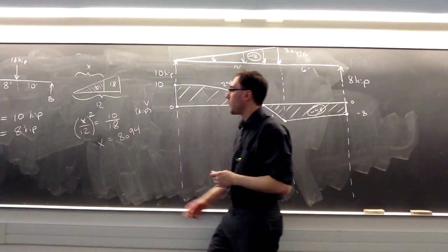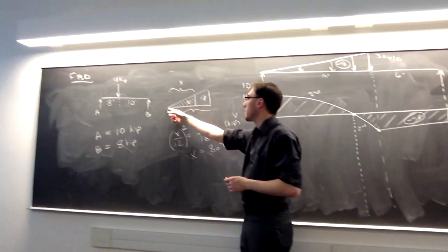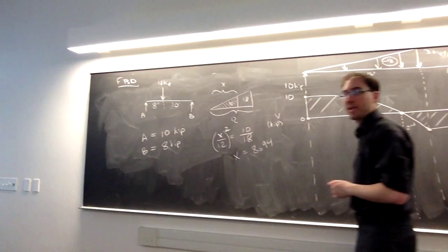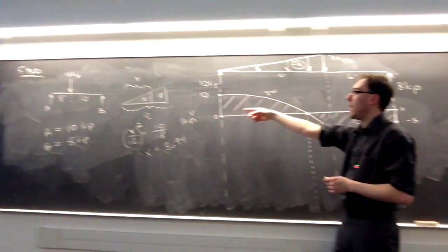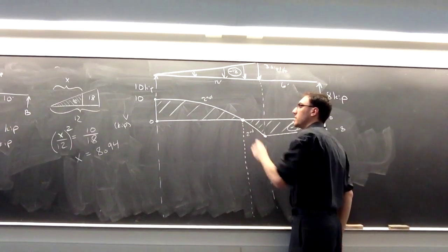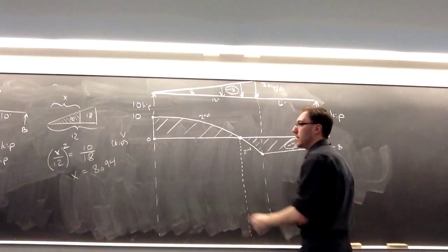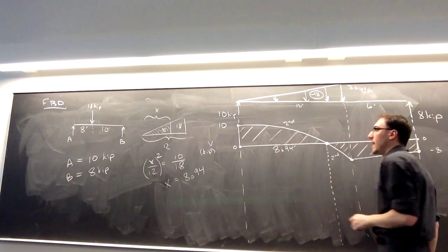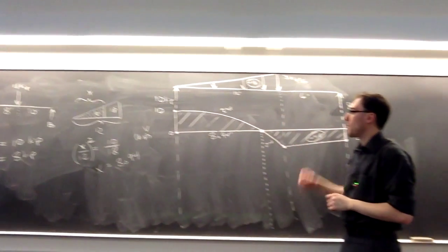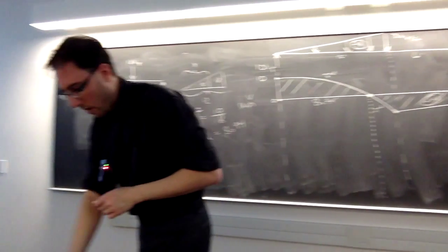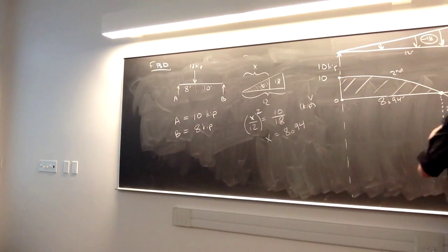Again, what does that mean? If we had a piece of the triangle that was 8.94 feet long, and we found the area under it, we would have found that it is negative 10, which means the value of V would have dropped by negative 10, which takes us to V equaling 0. That's the point of what we're doing here, to find how far it takes to drop to 0. And then the remaining is just going to be 12 minus the 8.94, or about 3.06.